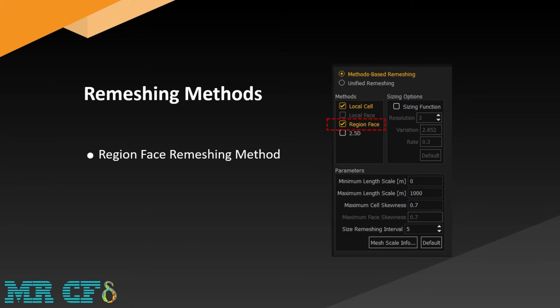The face region remeshing method is used to remesh triangular faces in 3D meshes or linear faces in 2D meshes that are on a deforming plane region and adjacent to a plane region. They are mobile. The software marks mesh planes based on maximum and minimum length scales and then remeshes those planes and associated cells to create a highly regular meshing on the deforming boundary.